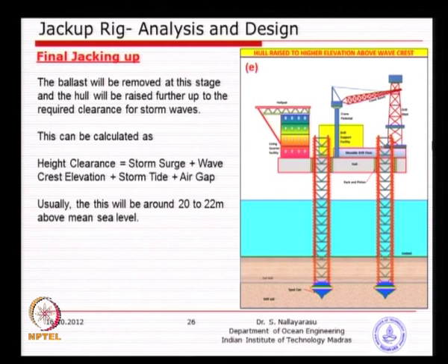Whereas here there is no special foundation, it is simply resting on the seabed, maybe penetrated a little bit into loose soil, because when it is penetrating, it is disturbing the soil, and the soil is quite loose. So, if you have larger forces applied at the top, it will just topple the rig and get washed away to shore. So, that is one of the biggest worries. Jackups have to be very careful. If a storm is expected, you had better evacuate, because you may not be able to survive that.